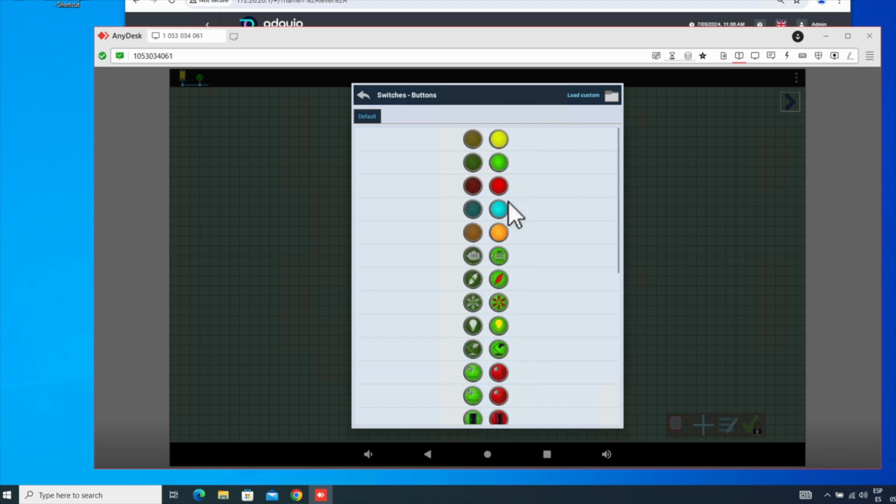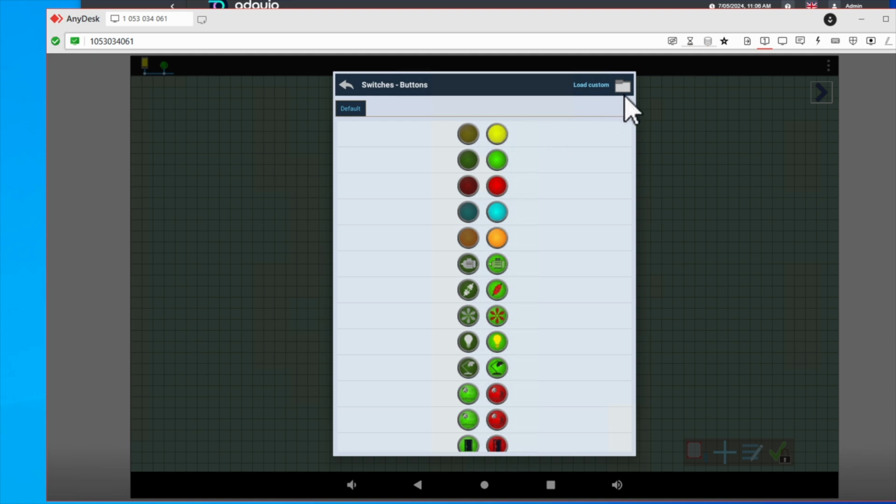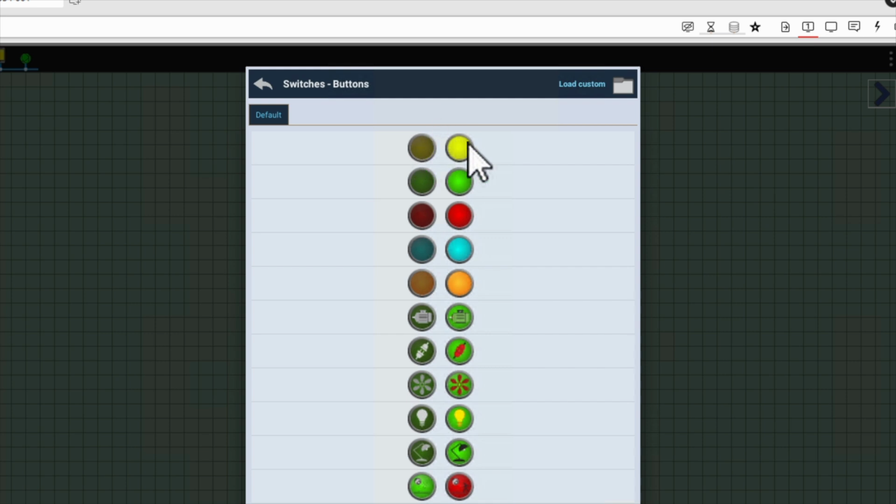Let's remember that we always have the option to upload our own icons, and we should always upload these icons in pairs, one for the inactive state and one for the active state. Later on, we will do an example, specifically not with icons, but with buttons, for example. But it's the same process. How to design a button, in this case, an indicator, to show if it is off or on. As mentioned, for two states, we will need to create an image for the LED off state and an image for the LED on state.